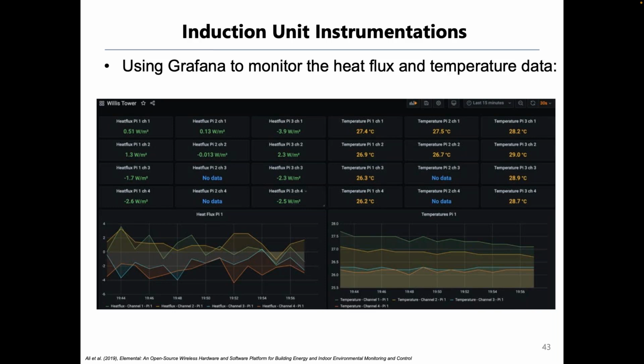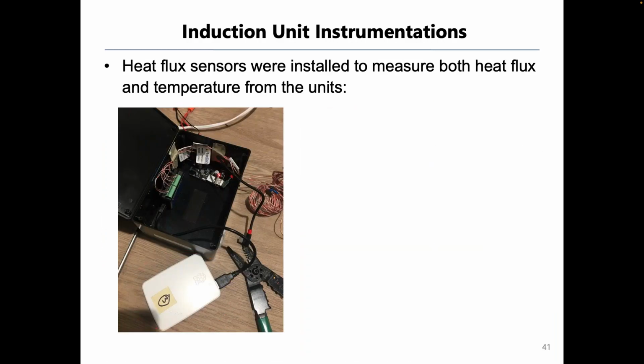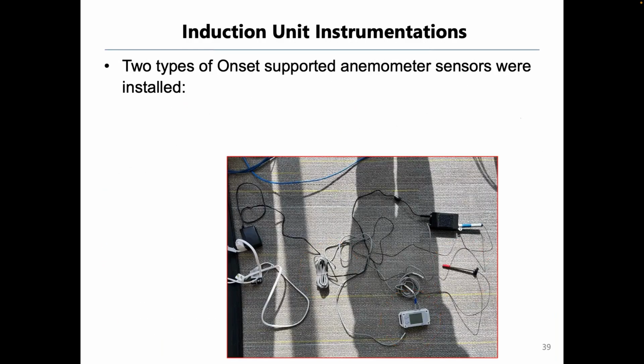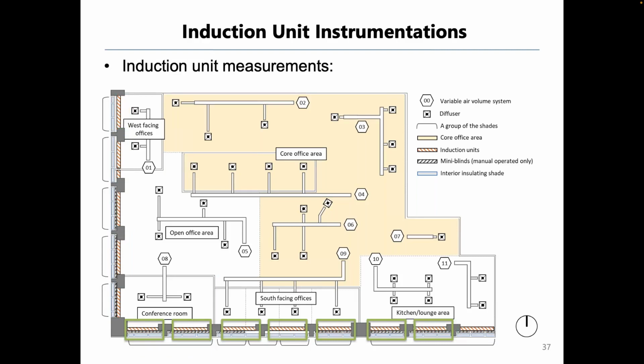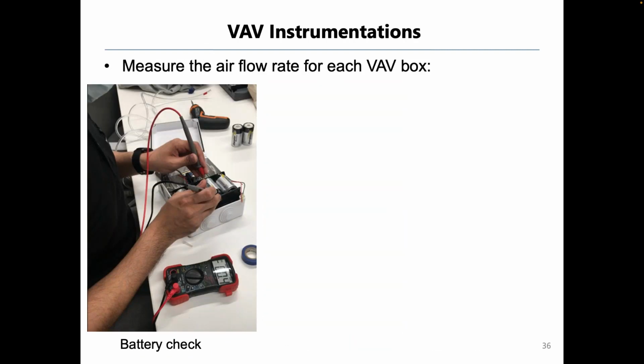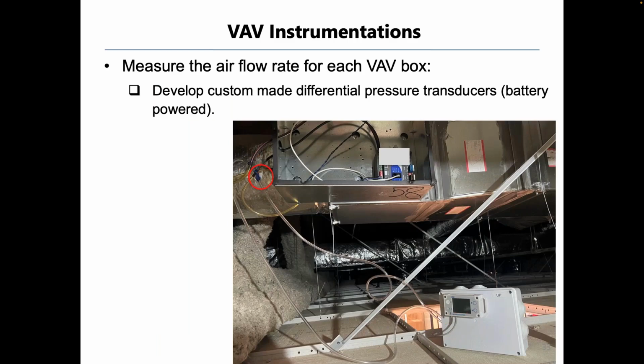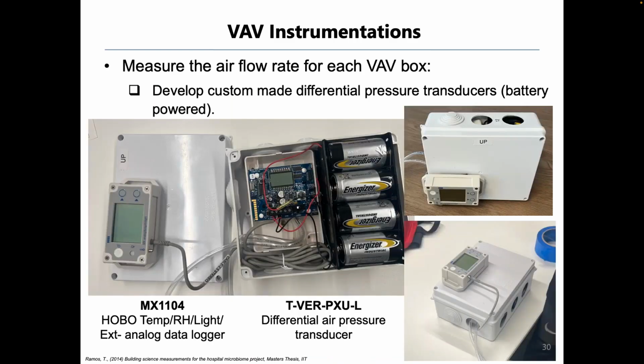Great. Yeah, and just so everyone knows, with our loggers, you can take in a signal from a third-party sensor. That's a 4 to 20 milliamp or a 0 to 5, 0 to 10, 0 to 24 volt DC signal. For the most part, if it's a sensor that we sell, then when you go into the HOBO Connect app, you'll be able to select the appropriate sensor, and it'll preload. Mohammad used some of our older Veris differential pressure sensors with a new logger, and you may have to enter the scaling values. And again, as long as it's a linear scale, you should be good.